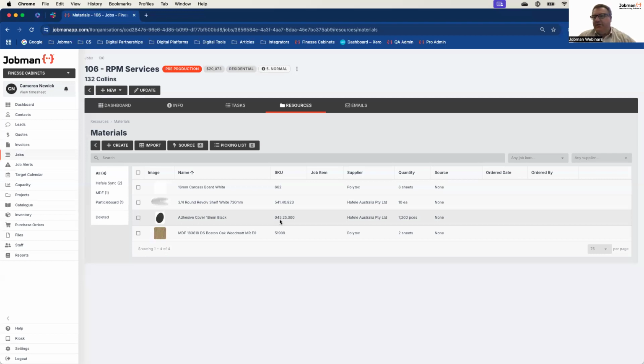The third way is, of course, the optimal way, which is for those of you who have the benefit of our CAD integrations, such as Cabinet Vision, Mosaic, Microvellum, CADmaster. Because there's a process between quoting and purchase ordering, which is generally called drafting or production drafting, detailing, however you define it in your business. That is the opportunity then to say, well, hey, we think it's going to use this much based on the quote, but when we actually nest and optimize those materials, we only need to order this much. And that's exactly what CAD is designed for.